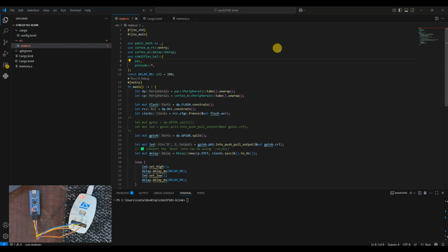In embedded systems, you must explicitly define panic behavior, since there is no OS to handle crashes. As we have access to the memory, reading and writing to registers directly using our code, we need something to handle such panic situations if we do some sort of null pointer dereference or something.